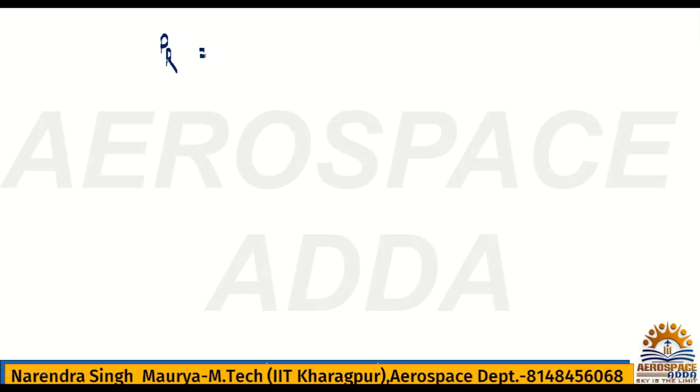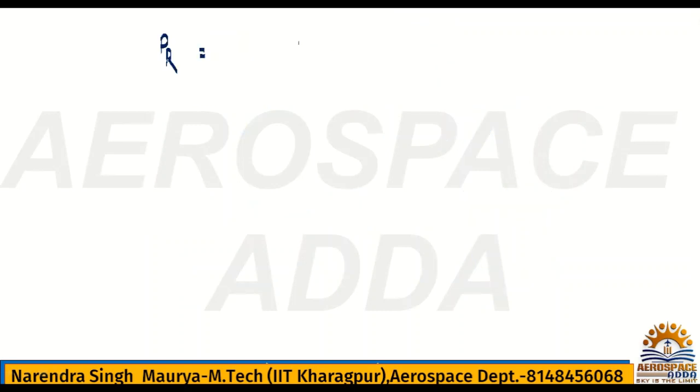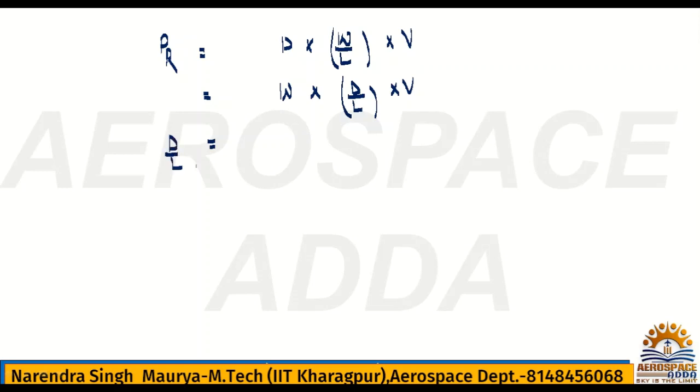Now check, what do we have here? Drag, weight of the aircraft, lift of the aircraft into velocity of the aircraft. So we can write weight of the aircraft, drag by lift of the aircraft, into velocity. Now we know this drag by L can be written as CD by CL, for constant altitude.